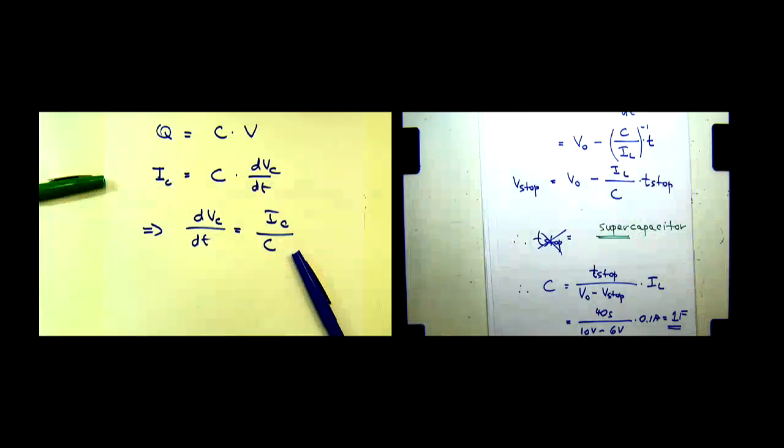Then look at the result and ask yourself, does this make sense? Here I didn't do that, right? I should have said, well, if I have a bigger capacitor, why would the voltage go down quickly? Makes no sense, right? So if you do that kind of thing, you can catch errors easily. You don't need to redo your calculation, make the mistake again. Use this sort of insight.